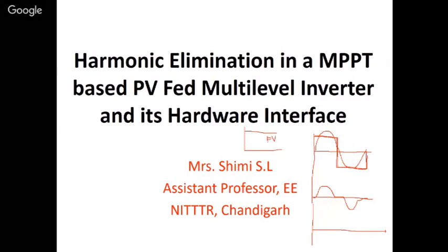There is the cascaded H-bridge multi-level inverter that you would have seen. Mostly cascaded H-bridge is good for renewable energy sources, so that's why we all would have discussed that. Apart from that, you have diode clamped and capacitor clamped. Two types, diode clamped, capacitor clamped, and then flying capacitor. The capacitor clamped is otherwise said to be flying capacitor type. And you have these cascaded multi-level inverters. These are the different types. Still, all would have talked about cascaded.